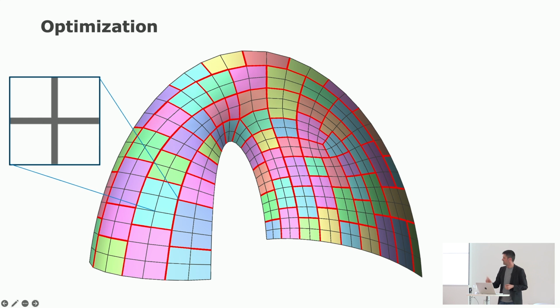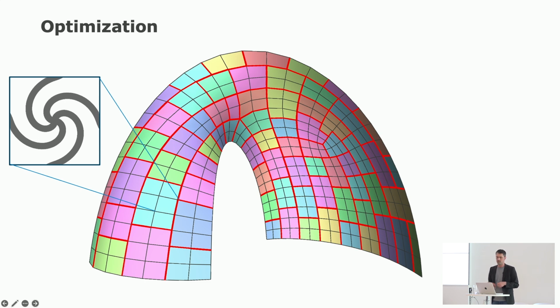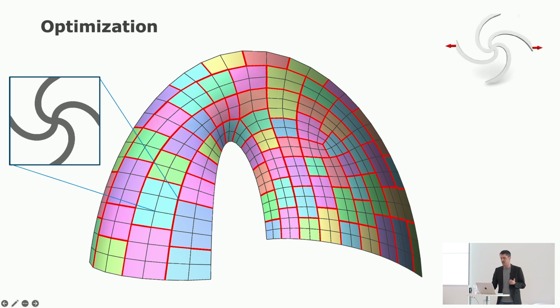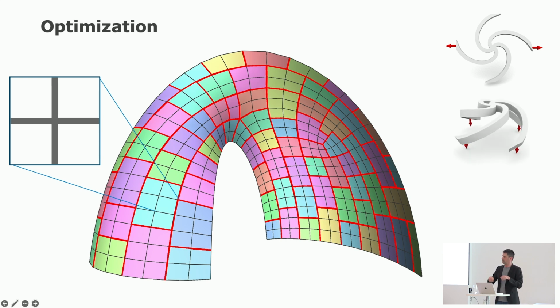The way it works is that for each quad, you have this cross, and then you start twisting it. And with this, you tune the mechanical property of it. We have a data-driven system, so a pre-computation that says, for a certain configuration, how are the forces when this is stretched, when this is bent, and also when these structures are twisted.